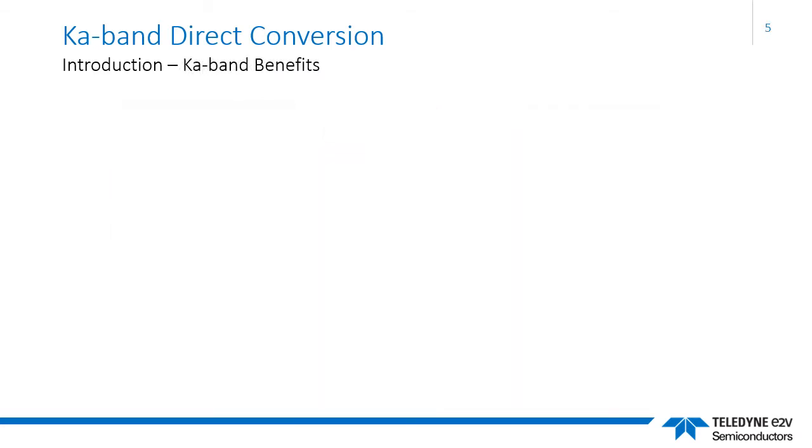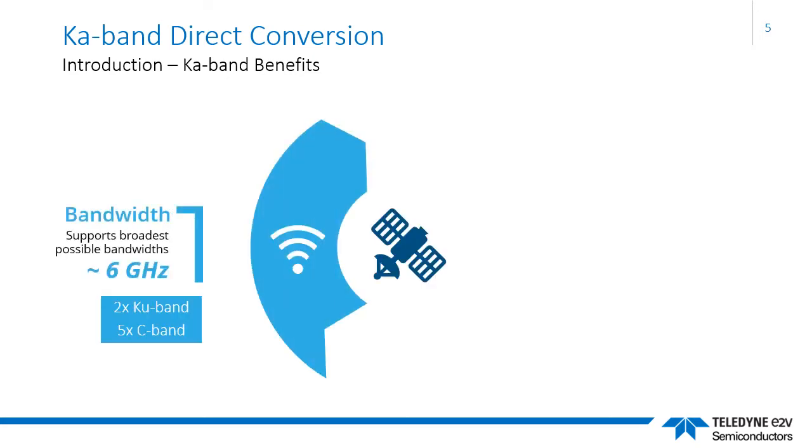What's special about Ka band? Probably the most important benefit are the wide bandwidth signals it supports. Ka bandwidths are double that of Ku band and 5 times that of C band. It's true Ka band is more susceptible to attenuation from airborne water droplets, but the space industry has already devised a multiplicity of solutions to this problem. One example includes ground station diversity, another exploits power and modulation schemes.